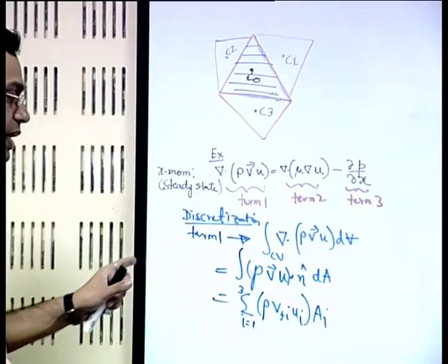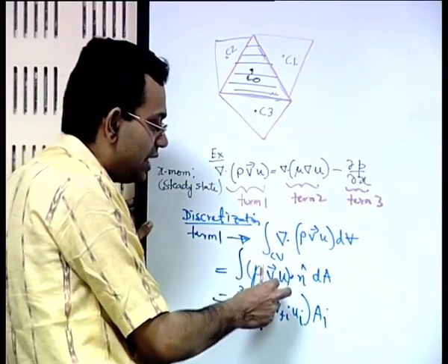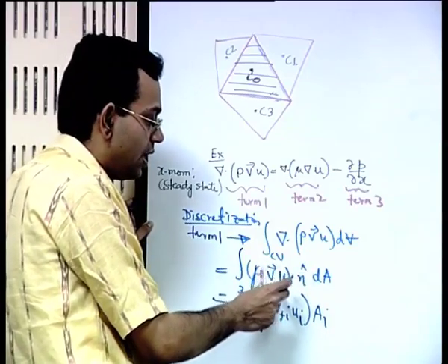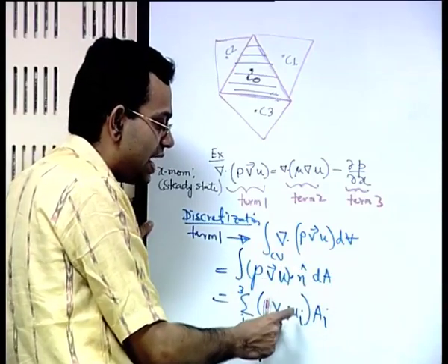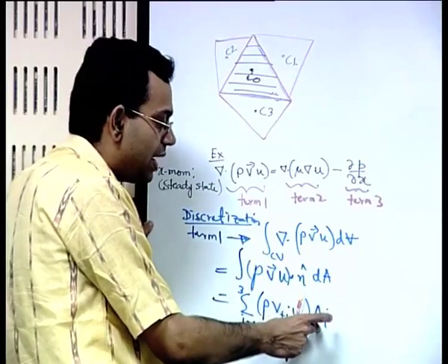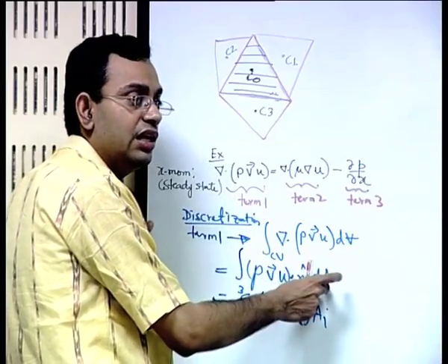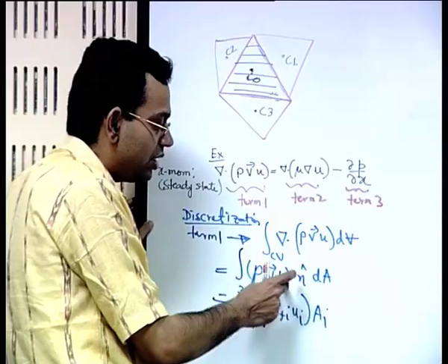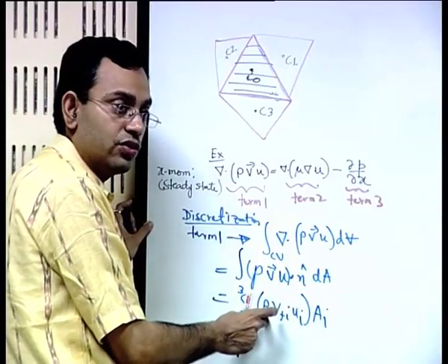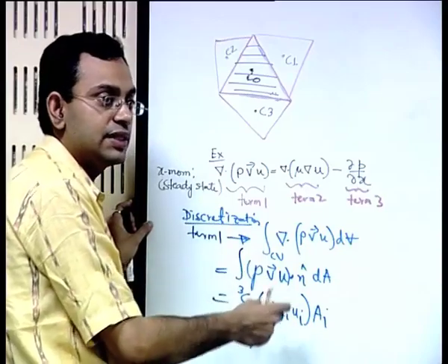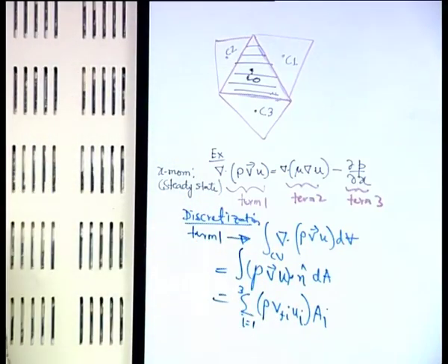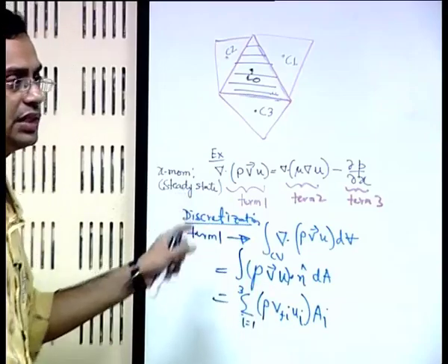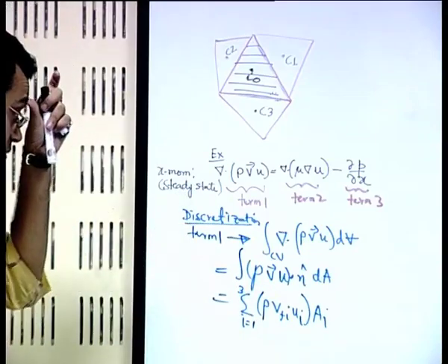What we are basically doing here is writing the normal component of the velocity across each face as Vfi, that multiplied by Ai is V dot eta dA integrated over that face, and for each face i we have the corresponding u as ui and rho remains rho, and we have it for 3 faces. This is just one way of representing this particular term. This term may be represented in several ways, but this is just one way of doing that.